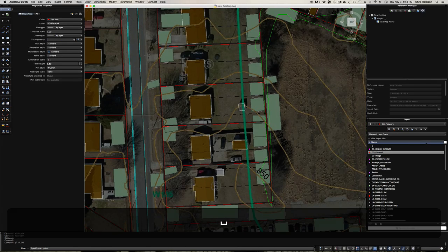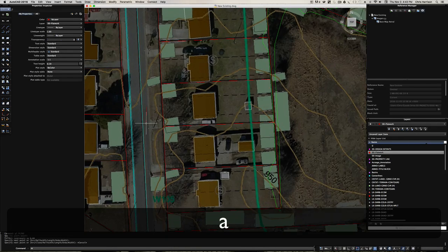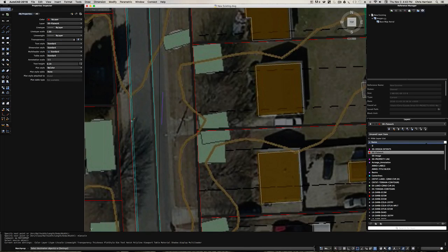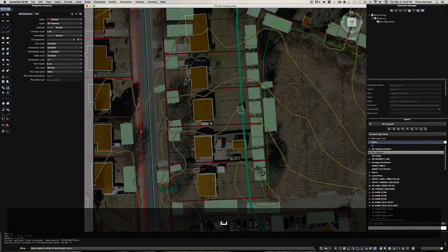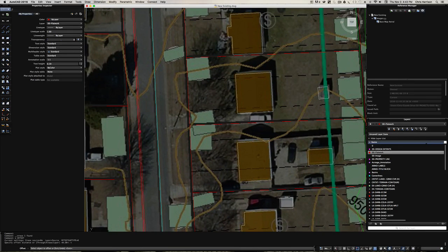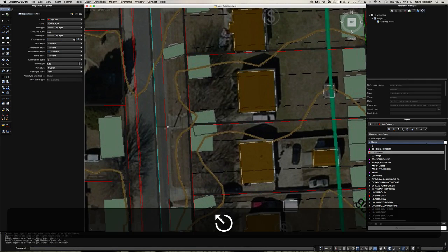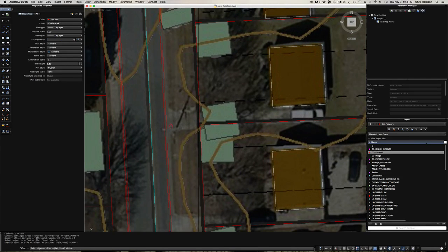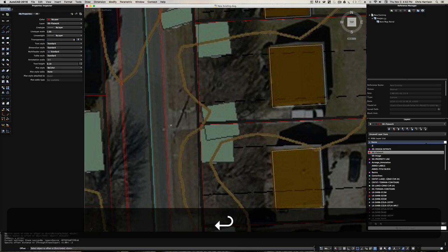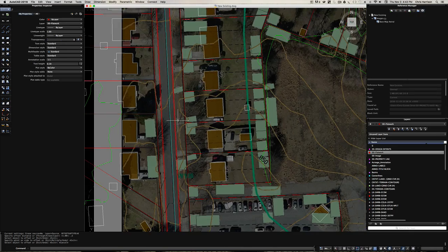Just do a PL real quick, and again, just do that same technique of matching properties, just MA, enter, click. And I'm just gonna change the properties of those lines because they need to be different from the center line. And then once you have that done, you can match properties from this thing very, very quickly. So I'm gonna offset through. I'm gonna use this one this time. I'm just gonna eyeball it because it is what it is. And then offset, and then 1 again for that edge of pavement. And then offset 0.5 if you're using this, boom, there, and then boom. So we have that kind of as a road line as I see it.